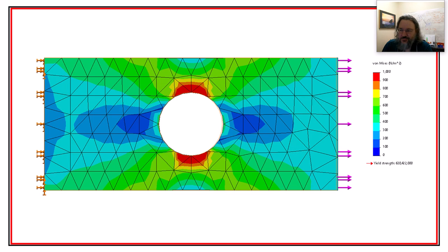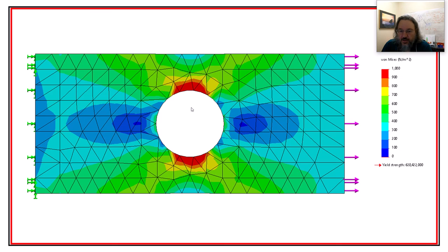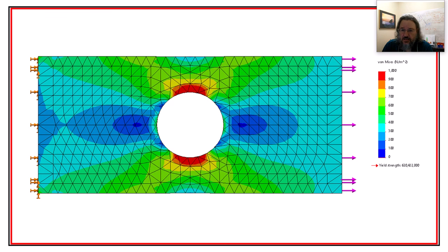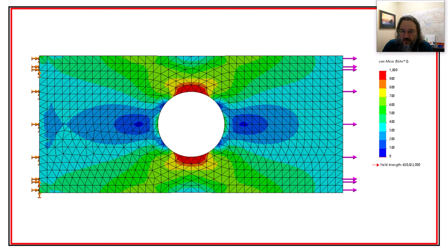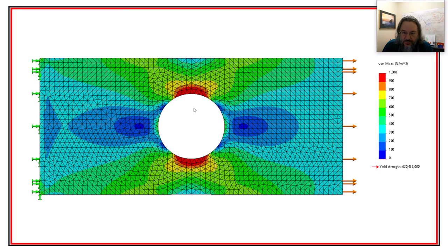So I just put a little circle on here, and I put a force of like 1 or something on there. This is a coarse mesh, and I refine the mesh, just as a demonstration of mesh refinement, right? So this is a discontinuity, and we'll talk about stress concentrations coming up when we start chapter 5. But this is a stress concentration, and we could actually look up in a book and see what the known expected stress is going to be. But you can see that it's changing, and so here's a more refined mesh and a more refined mesh as we're coming up here, and you can see it's starting to look good, but it's really the actual values that we care about.